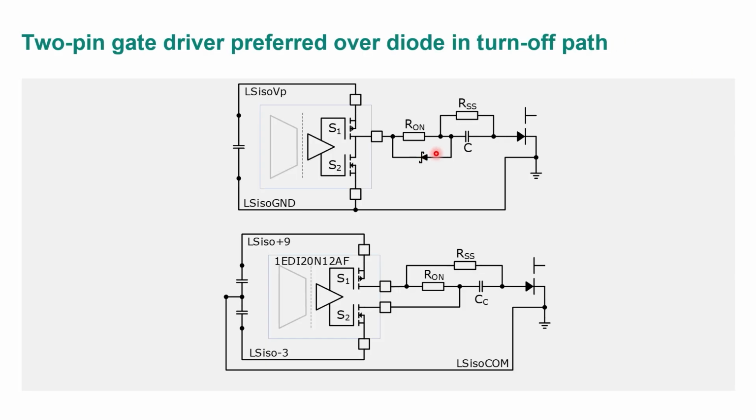I mentioned the diode and the return path. If I use a gate driver that only has a single drive pin, both sourcing and sinking current, I have this problem that I can't have a separate impedance, a separate resistor for the turn on versus turn off direction. So I only have a single resistor. I can bypass it with a diode or I can bypass with an RC. You can do this, and this is very commonly done with silicon or with other high threshold transistors. What's the problem if I try to do that with GaN?